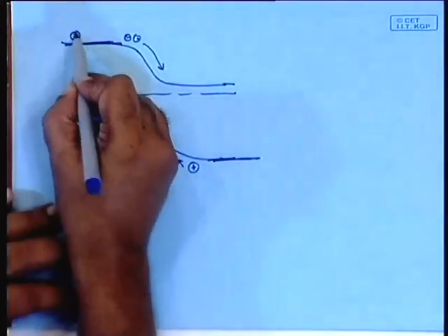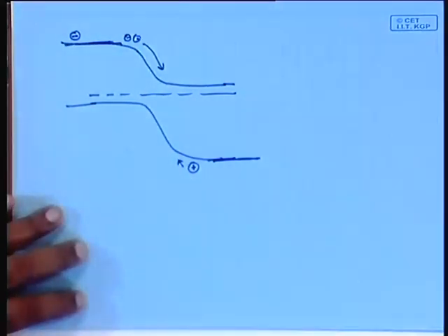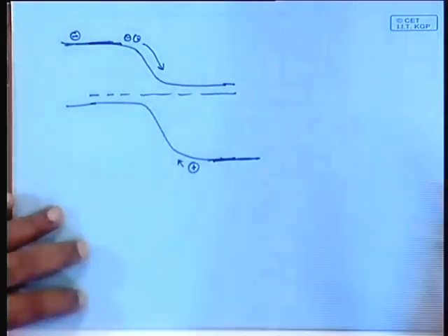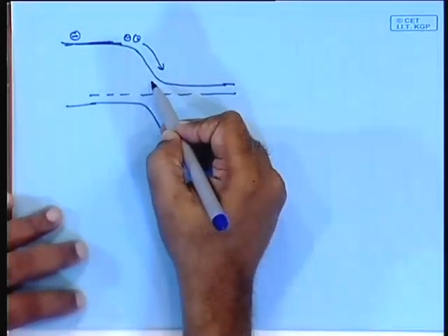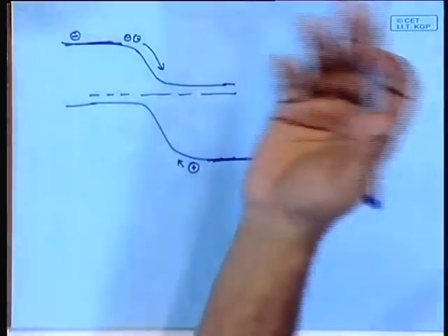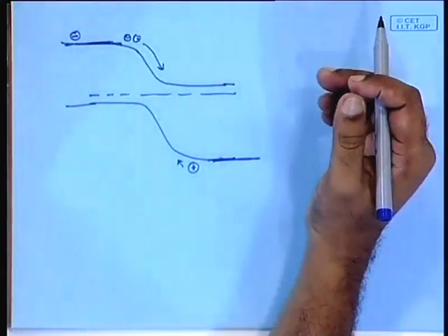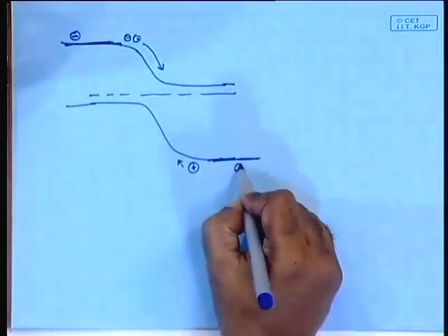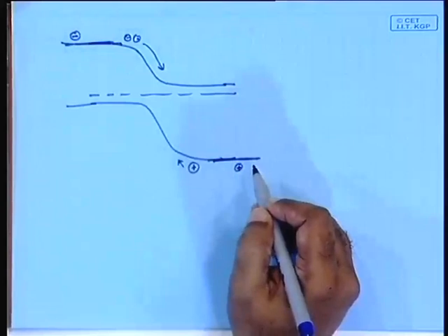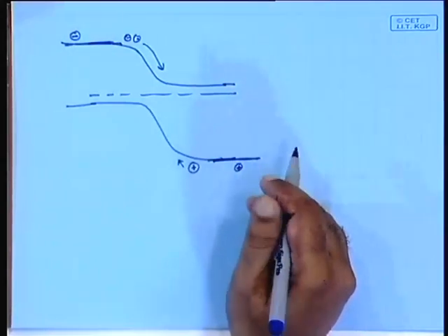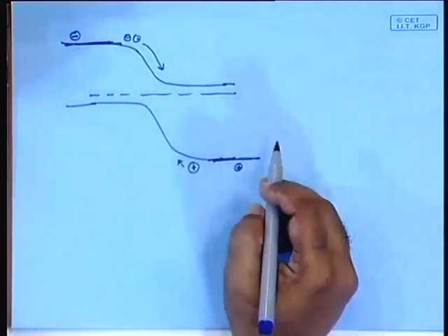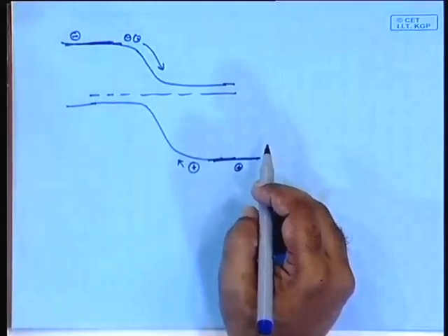If it is flat here and some electron is produced here, what will you see? We will not be able to see, at some distance there is a band bending. So, it will actually move in any random direction, it will not flow down the hill. If a hole is produced here, same problem. So, normally one way to avoid this is to produce a graded doping.